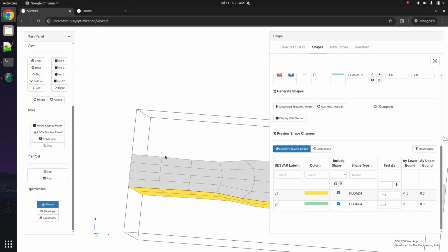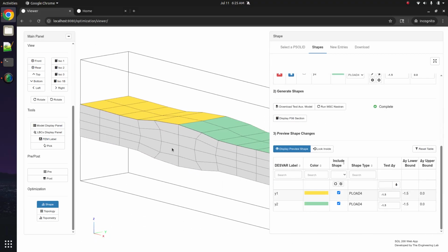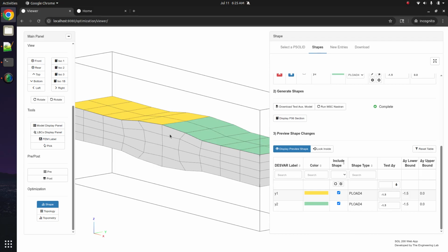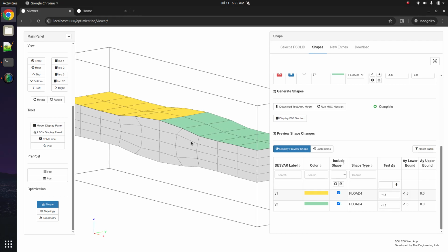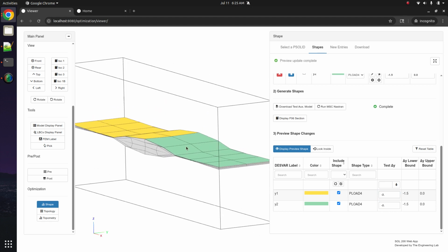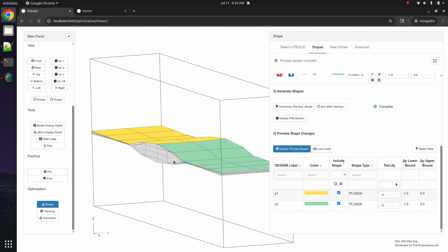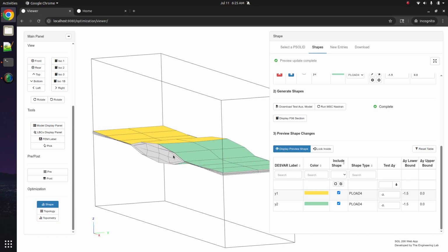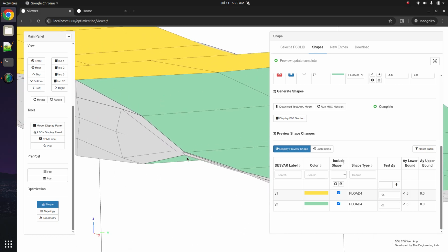Okay, now let's go ahead and talk about the bounds. The bounds of the variables are very important because they're going to prevent the mesh distortion. Here, let's go ahead and experiment with a shape change of -2 for both shapes. So what happens if the variable changes by -2? Here you can see that if the lower bound is ever -2, we'll most likely get a shape distortion.